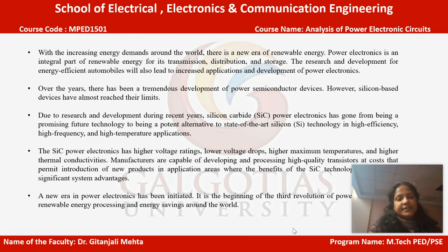Silicon carbide power electronics has higher voltage ratings, lower voltage drops, higher maximum temperatures, and higher thermal conductivities. Manufacturers are capable of developing and processing high quality transistors at costs that permit introduction of new products in application areas where the benefits of silicon carbide technology have significant system advantages. A new era of power electronics has been initiated. It is the beginning of the third revolution of power electronics in the area of renewable energy processing and energy savings around the world.